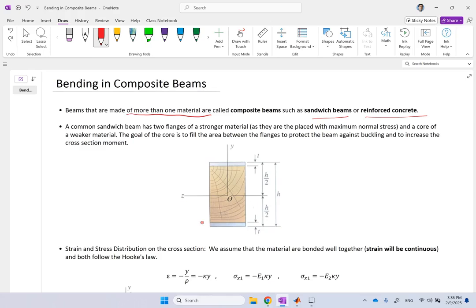Of course, but remember that, first of all, aluminum is heavier than wood. So it makes the whole beam heavier, which adds to the stress. And also, of course, it's more expensive, so it adds to the cost. The other thing, if you remember, sigma is maximum at the top and the bottom. If this is the neutral axis, the normal stress distribution is linearly increasing from 0 to the maximum at the top and the bottom, right? So here it could be compression, it could be tension, or backwards, but basically this maximum load carrying part of the cross section is the top and the bottom portion.